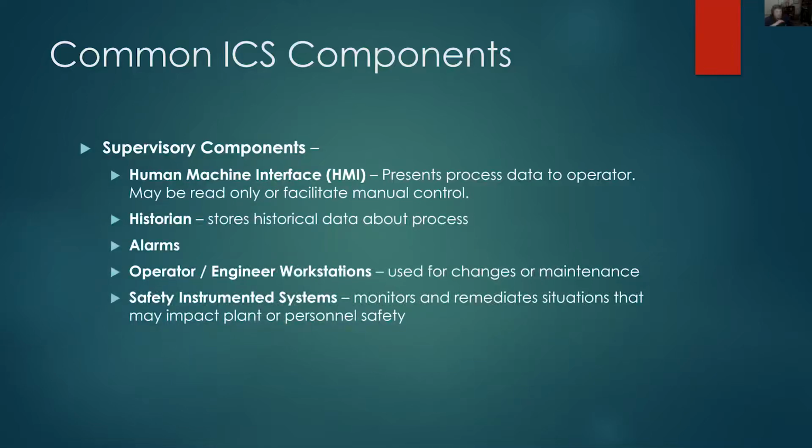And then that will get converted into a series of values and pushed down to the individual systems, and that's how they get programmed. And then the final one is the safety instrumented system, and that did not show on that Purdue model diagram because that exists below everything, and usually they are wired separately and kept off the industrial control network and off the corporate network. They're their own separate thing for safety's sake. And we'll come back to that here in a little bit.